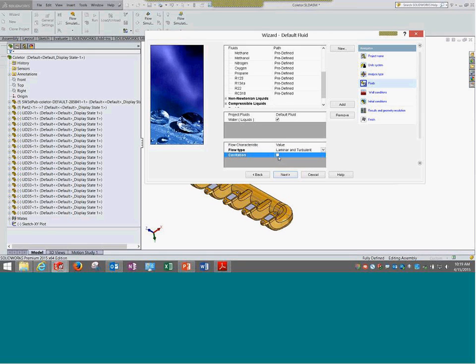Next, another phenomenon, of course to come later, but to put it simply, you expect the pressures to go very, very low, and it can lead to vacuum at those locations, and it can lead to a phenomenon called cavitation. Then just activate it. This will clear those complexities and solve the entire setup appropriately. It is not going to help you visualize cavitation, but it is only imbibing those effects into the software. We need to understand cavitation only from the pressure distribution or variation.